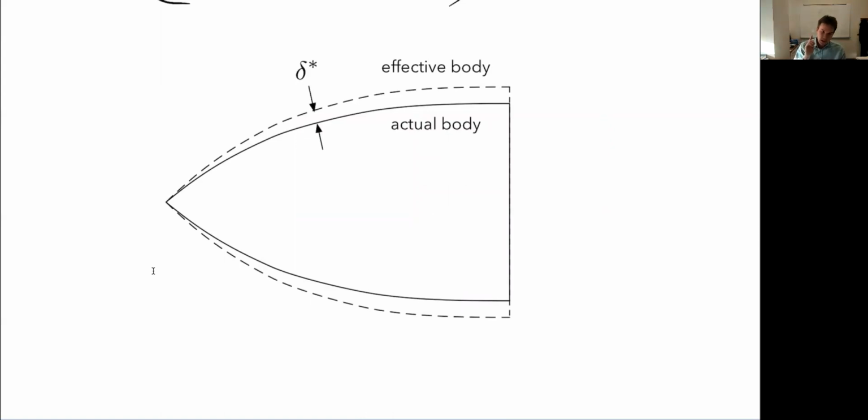So in other words, let's say I solved my inviscid solution over this actual body. This is the shape of my body that I solved for. I computed the inviscid solution, so I get the pressures, I get the edge velocity. With that inviscid solution, I can now go and compute my displacement thickness everywhere. And I could then increase the thickness of my body everywhere according to delta star. And that's now what the inviscid flow solution, to be more accurate, is really seeing. It's an inviscid flow around a body that's actually a little bit thicker because viscosity is decreasing some of that mass flow. So if I want to do this well, then I should make the body bigger and then go back to my inviscid solution and resolve it now with this body that's a little bit bigger because of that displacement from viscosity. So we could do that, we could iterate.